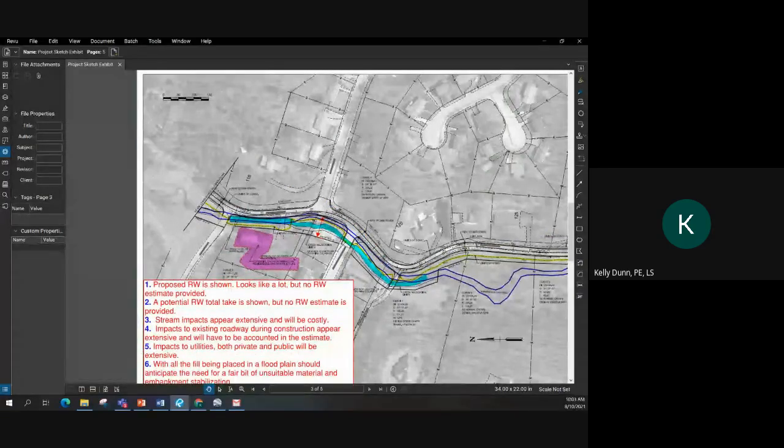While a lot of the project as shown is to be constructed in fill and may therefore be thought to only slightly impact these underground utilities, the applicant should consider the depth, age, and condition of these underground utilities to determine if they will be able to maintain their integrity during compactive efforts of the placed fill.